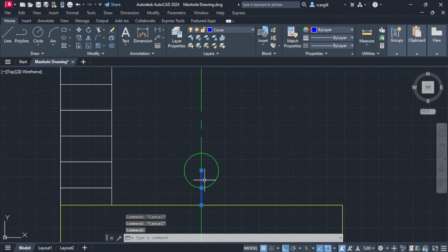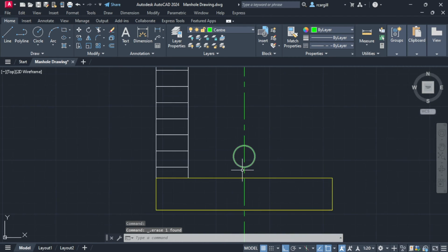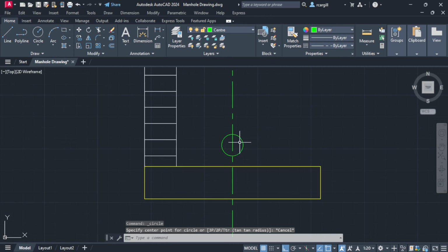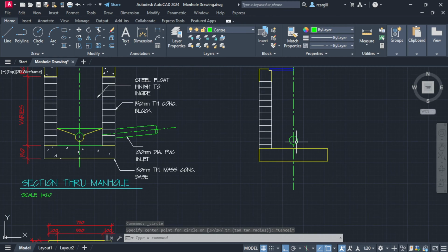I no longer need this line here. You didn't need the line to get the center. You could just select a circle, come here, and just move your cursor up, type 100. It gives you this point, then you can draw the circle. So you could do that also. All right, so I have this now. So what I'm going to do with this from here is this now.